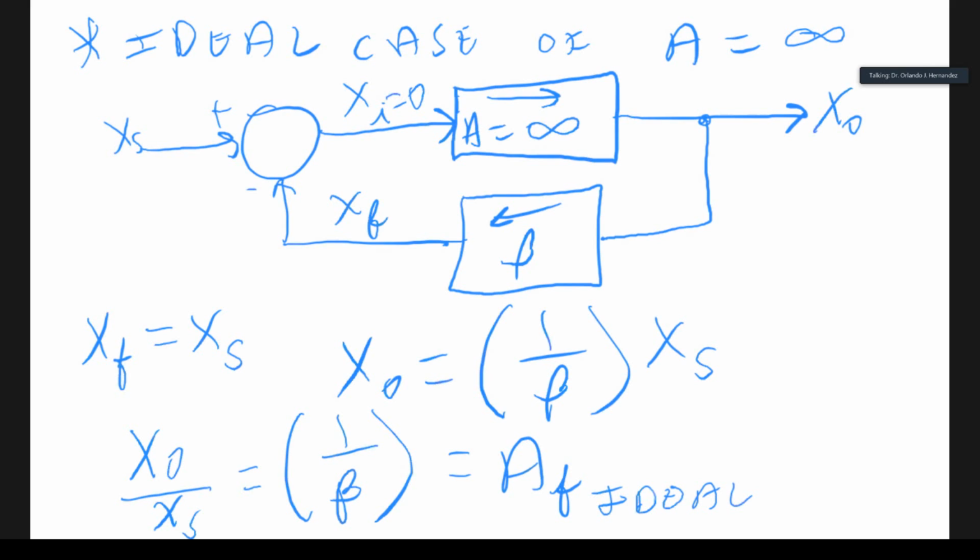And luckily, the nice thing is that since we can use feedback to make our system less sensitive to that gain that we want high, but which is also varying widely, we can use feedback to desensitize that gain. We can make our circuits useful. So let's look at that property of negative feedback in terms of making our system less sensitive to the high gain.